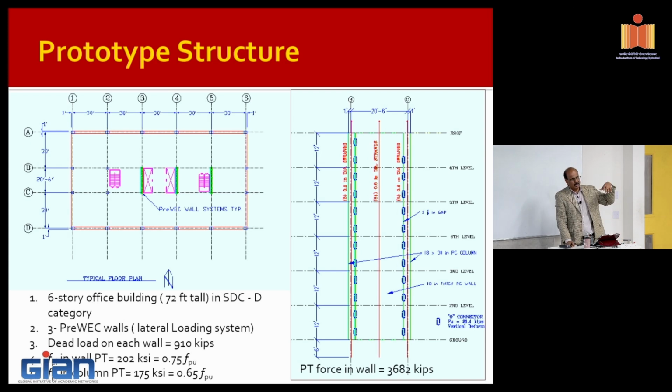The second set of walls, what we wanted to do was eliminate all of the connectors in the structure and say, okay, we provide zero damping through hysteretic action. You just rely primarily on the inherent viscous damping and the impact damping. If you do that, will the wall survive? That's a good question to ask, because if they survive, they are going through less damping.